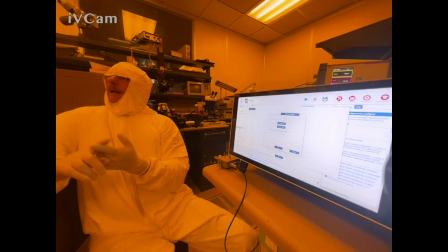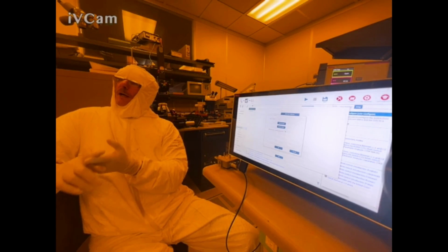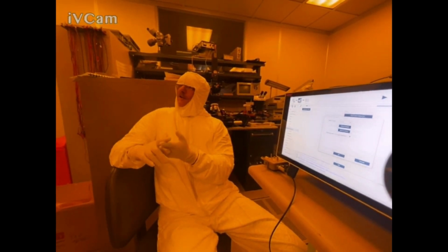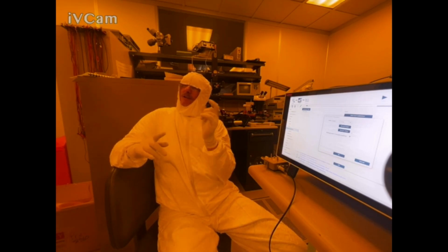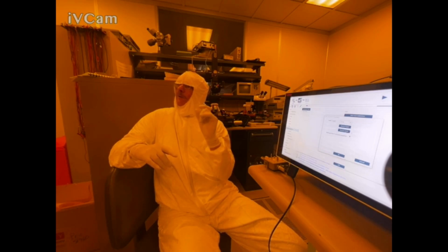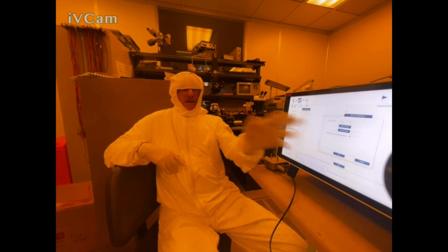Open compensation is the most important for you guys, okay? Because you need to do open compensation when you're measuring small capacitances, which is what you'll be doing, right? You're going to measure low capacitances. So low parasitic capacitances in parallel are going to matter to you, right? So you need to get rid of those.